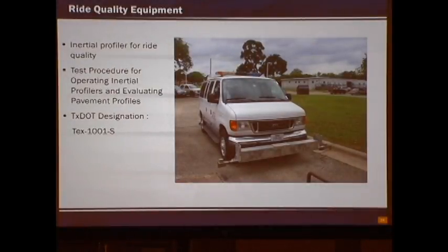To perform this test, we used an inertial profiler for ride quality. The test procedure for operating inertial profilers and evaluating pavement profiles is the TxDOT designation TEX 1001-S.